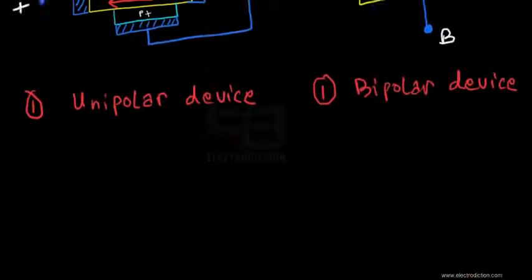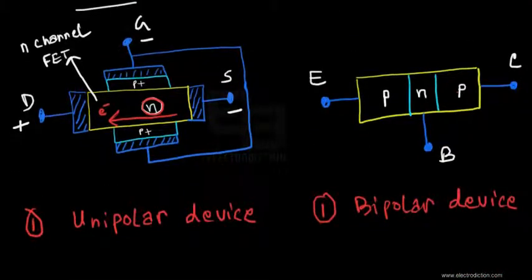Having that said, if we take another look at the two diagrams, we can see that in order to operate the JFET, the diagram we're using here for reference, the gate terminal needs to be reverse biased, in the way that it should be.